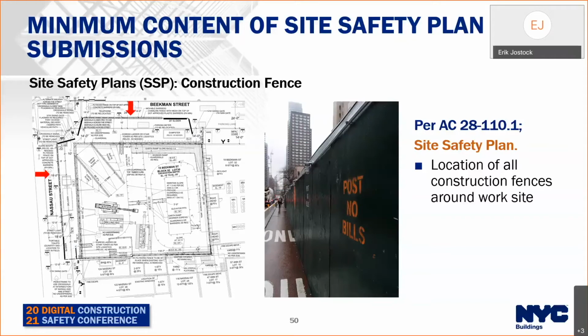BC 3307.7.1 specifies the requirements for fence location. Fences shall be installed so as to not unreasonably obstruct, either visually or physically, traffic, curb cuts, vehicle access points, street light poles, traffic lights, fire hydrants, fire department connections, water sampling stations, bus shelters, other street furniture, trees, or means of egress.